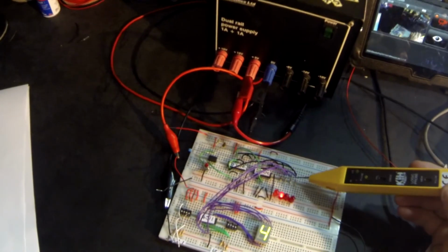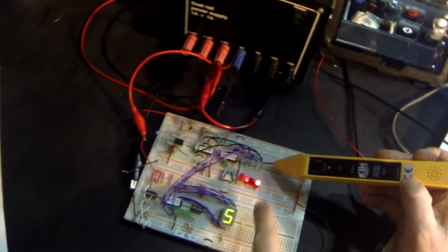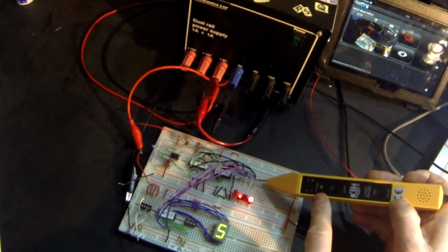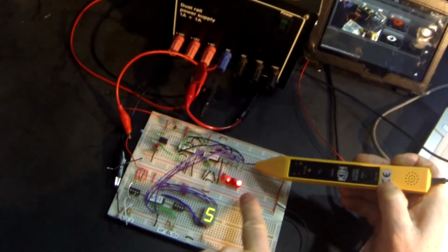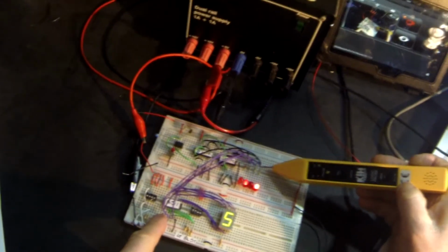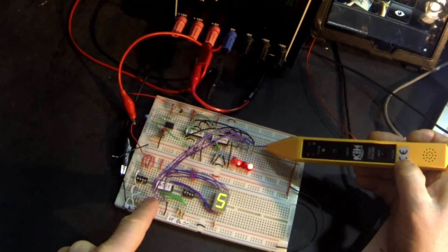Just as a quick bit of testing, it might be worth looking at that when it's low. And you'll notice that when the LED is on, that is not recognizing that as a high because of the voltage drop, but it seems to be enough for our 4511 to recognise it as a high. This is sometimes the conflict between analog and digital circuits. But this is the end of this tutorial.